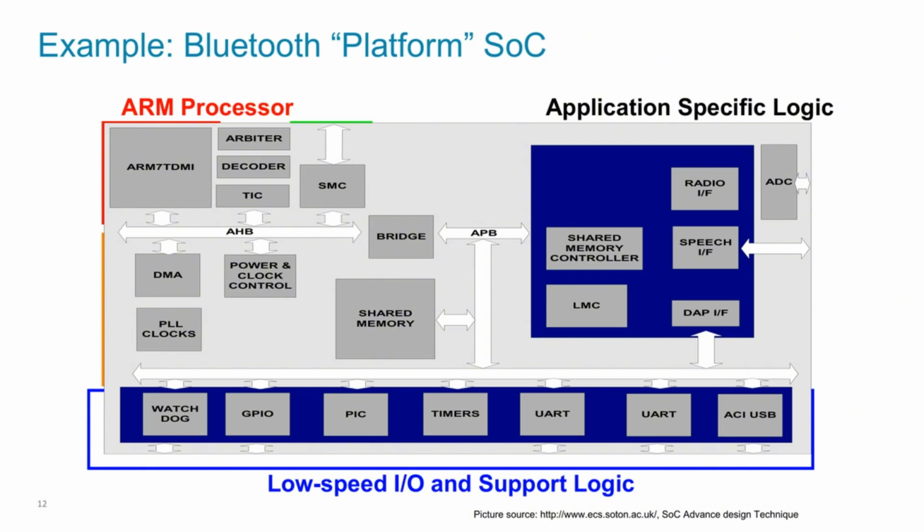First, let's look at the part in the red box labeled ARM processor. This is the brain of the entire operation. At its heart is the ARM7 TDMI core. This is a specific, well-known ARM processor that was very popular for embedded systems. It's connected to other critical components on a high-speed bus called the AHB, or Advanced High Performance Bus. Think of the AHB as the main highway inside the chip. Everything that needs to communicate quickly uses this highway.